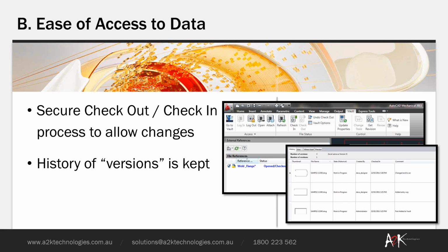So for example, if it is work in progress, it gets released to the shop floor. Someone in the shop floor notices a mistake, sends it back to work in progress. Well, then that would go to the next revision. So versions are created every time a file is checked in and out, and revisions are controlled via either the lifecycle state in the workflow or manually bumped up by the engineer and the designer.